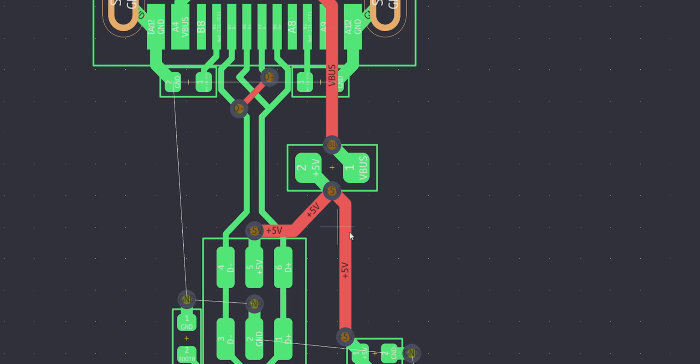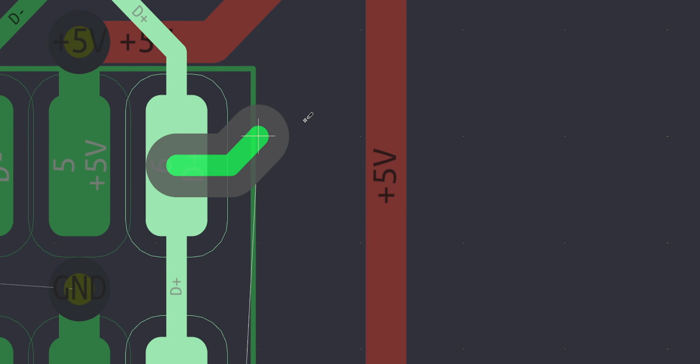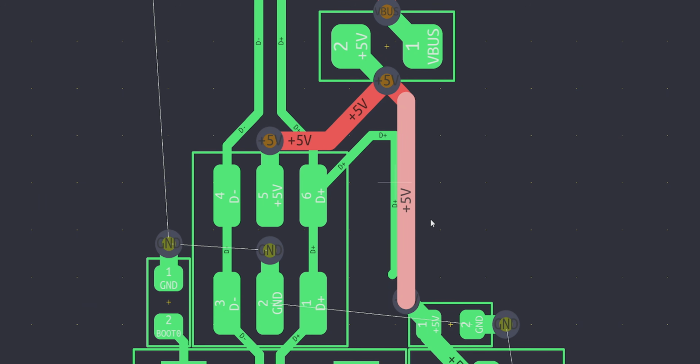It has to do with this line here, this voltage line, like I said earlier, where you want to keep those away from any data stuff. If say I wanted to run my data line right like this next to it, there's the possibility that this voltage line creates EMI interference on this. Whereas if you had a 4-layer board, you'd have those 2 inner layers to prevent that, where they would basically block all that possible EMI, electromagnetic interference, so you wouldn't have any issue.